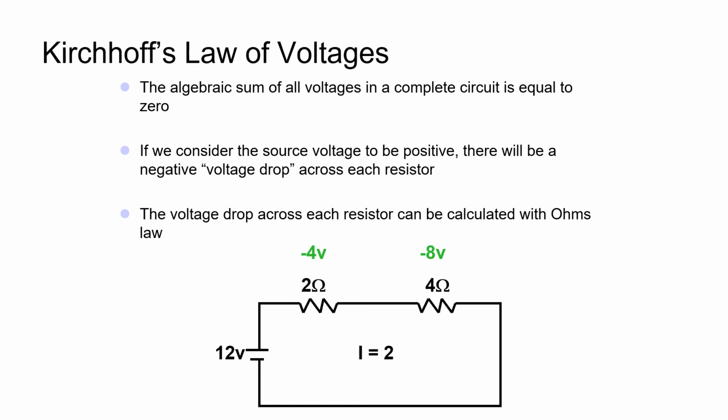Similarly, if we have 2 amps of current that flows across a 2 ohm resistor, there will be 4 volts that drop across that resistor. We have 8 volts drop across the first resistor and 4 volts drop across the second resistor. We then have 12 volts that have dropped throughout this circuit powered by a 12-volt battery, confirming Kirchhoff's law.